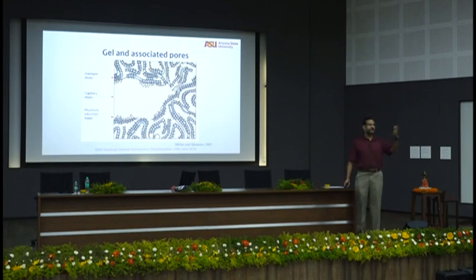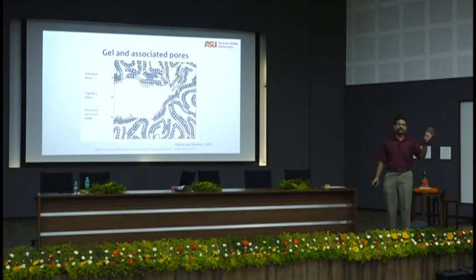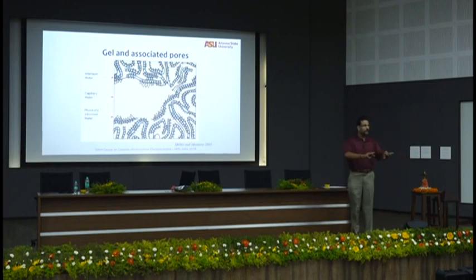Capillary pores, so every textbook will tell you, are larger pores, and when water goes out of a bigger capillary pore, no worries, you won't have that much shrinkage. But now listen very carefully: water going out of this capillary pore means what for the waters around it? You have reduced relative humidity around that location, and what does water always want to do? Equilibrate, right?